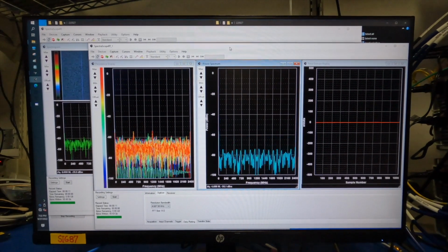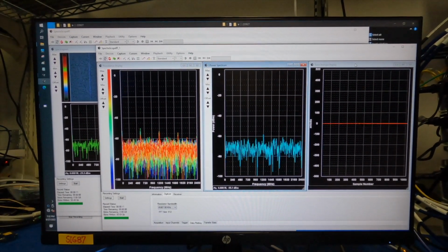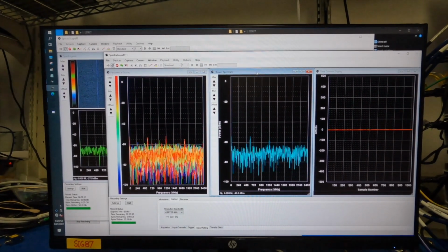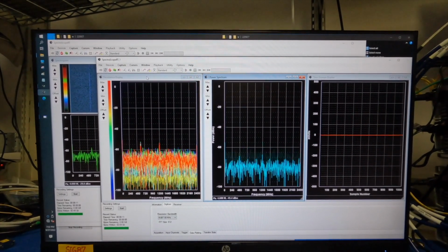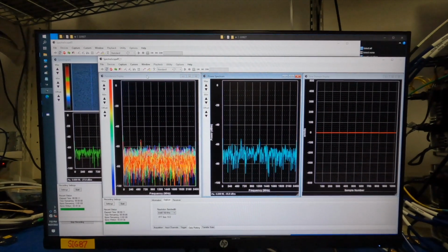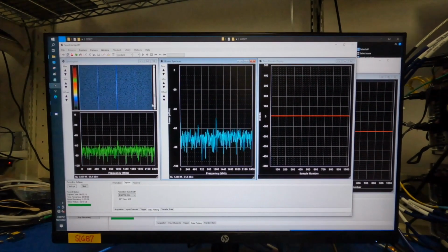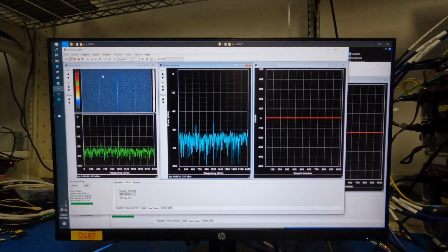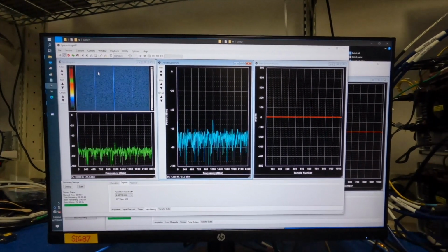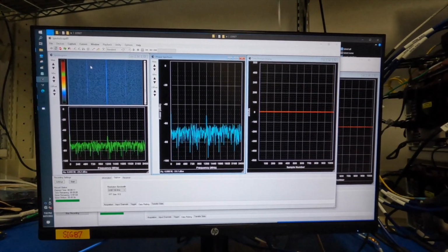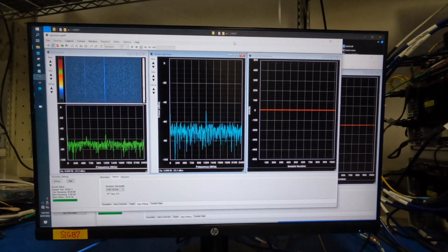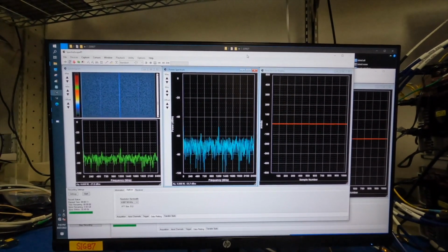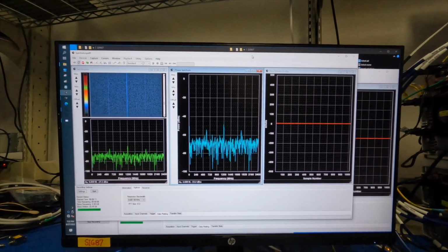I just wanted to show you a couple of varied displays. We have a time domain display, an FFT, fast Fourier transform frequency display, and then this particular one is a persistence display, which you guys are all familiar with. Another history in time display is also the spectrogram, which gives you amplitude versus frequency versus time. And in just a second, we'll turn on the RF threat emulator, which is actually going to put a signal in to be displayed and captured.